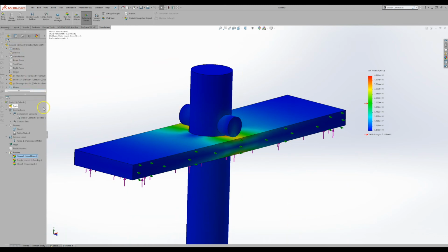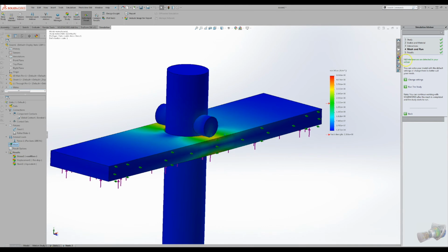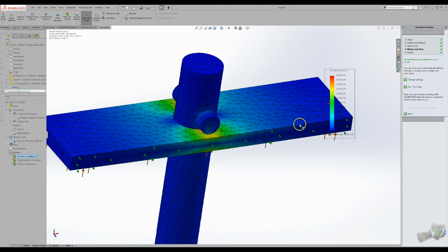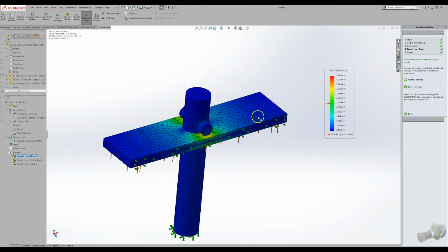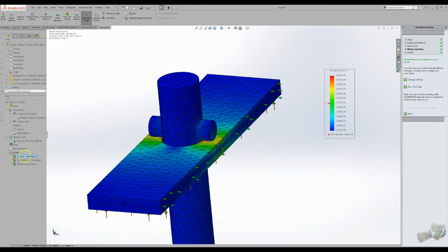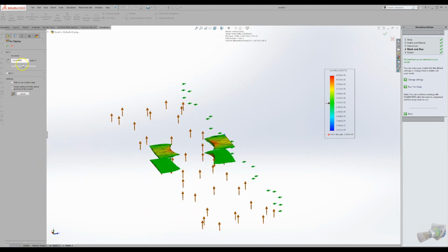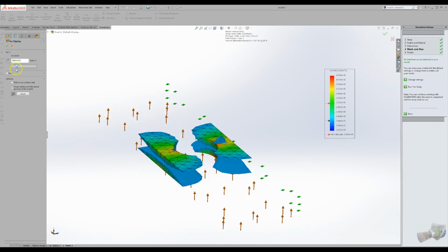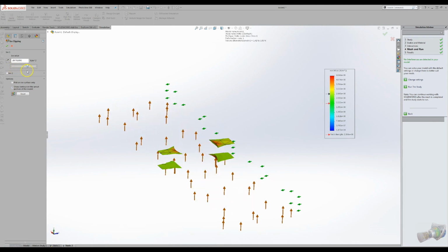You'll notice that green roller slider there is allowing the bar to bend upwards, but it's stopping it from spinning. If I was to put a roller slider on the end, then that would artificially constrain the bar, and we wouldn't get necessarily realistic deformation. But here we can see that that mesh is ridiculous. If you look at the red spots, yes, they are singularities, and I've iso clipped here just to highlight that, but there's hardly any elements within the high stress area that I'm interested in.